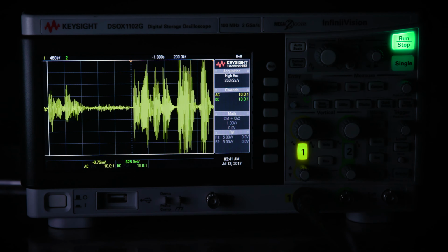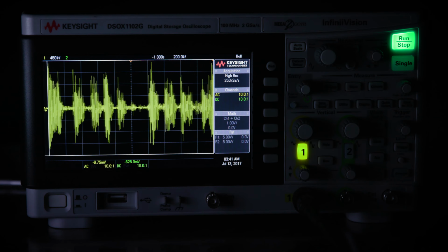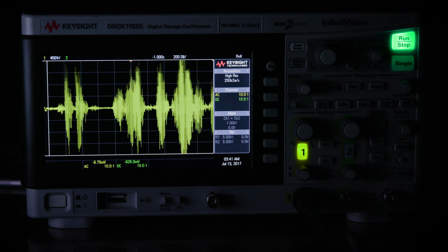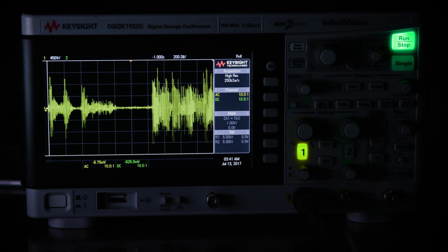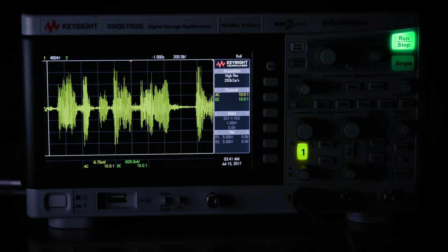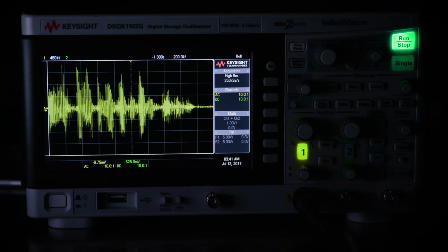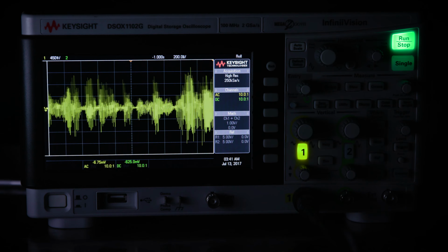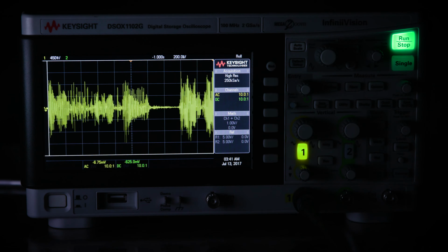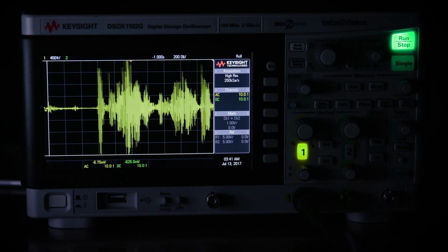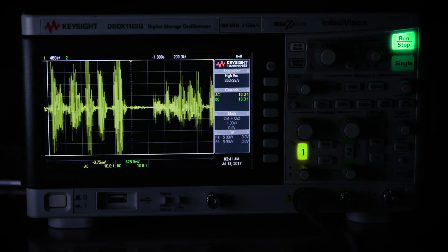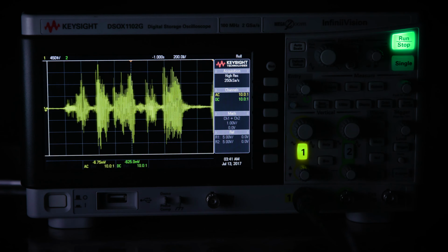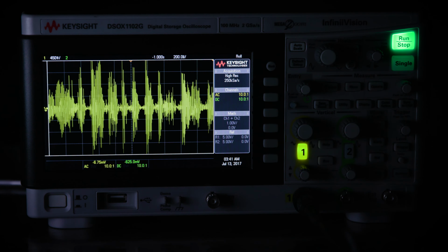But as you get into some folding architectures and some successive approximation type architectures, you can get more significant bits that are off. So instead of getting 36 or 37, you accidentally get 37 plus 128. Every once in a while. So if the 4th bit is off instead of the 8th bit off. They may not matter that much in a communication system, where if they happen once in a billion, once in a trillion times, the chance of them forcing an error that the communication system can't recover from is small.